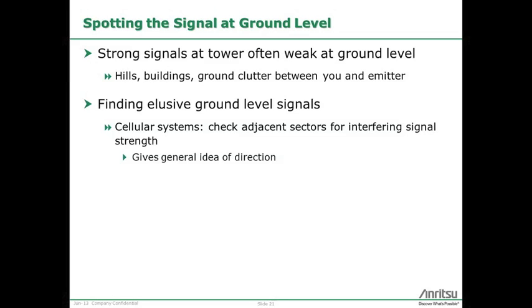So some hints. Just like we talked about, check adjacent sectors for the interfering signal strength. That can give you a rough idea of bearing. Or even from a different cell, you can get a relative signal level and maybe a rough idea of the distance between the cells.